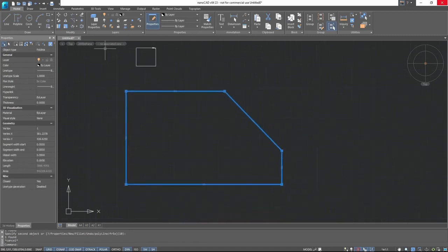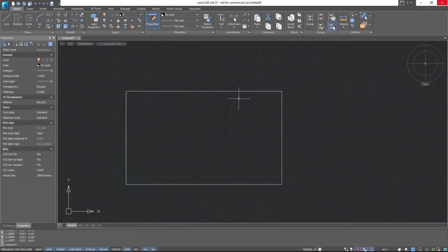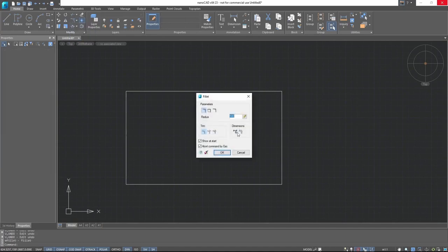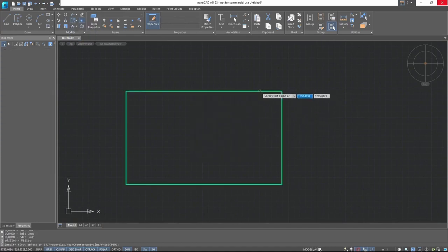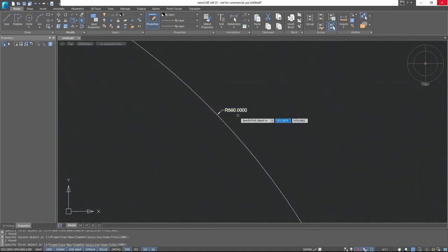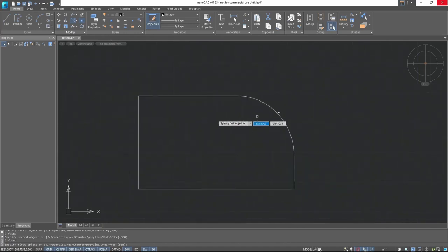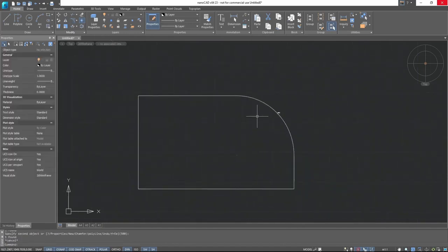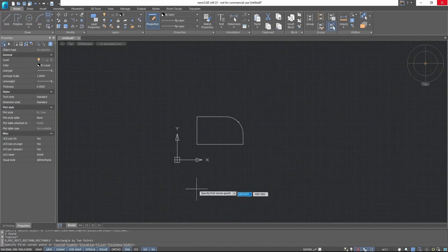If it's a fillet, the radius will be indicated. Fillet. Dimensions. OK. This is how these two commands work. You can also set up chamfer and fillet while drawing a rectangle. Chamfer and fillet. And the parameters you enter in the command line will be applied when creating future rectangles.